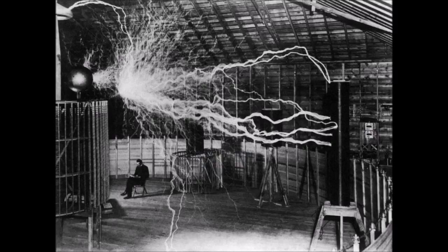The alternating current energizes a copper wire coil in the transmitter, which generates a magnetic field. Once a second or a receiver coil is placed within proximity of the magnetic field, the field can induce an alternating current in the receiving coil. Electronics in the receiving device then converts the alternating current back into the direct current, which becomes usable power.